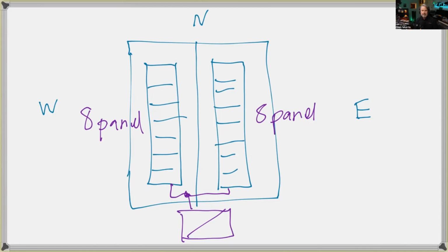Now, for the MPPT, if they write there 80 amps, 24 volt, that means if we times 80 times 24, we get the power input to the controller, the MPPT, in watts. If you times 80 amps times 24, we get about 1980 watts. That means the MPPT can only take 1980 watts maximum.